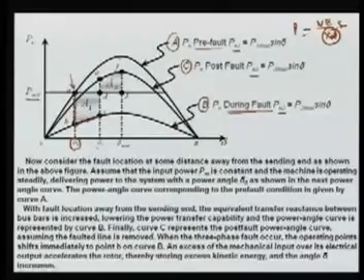Let's suppose at delta 1 your fault is cleared, and this fault clearing is associated with this tripping of the line, means suddenly we have to reach the post fault condition, that is point E of this curve, that is the post fault curve C. And then what will happen, this is your accelerating energy, this curve, then here it is going to decelerate till F, till the point when the A1 will be